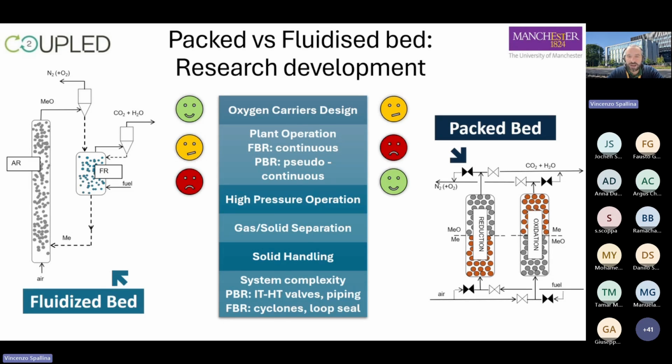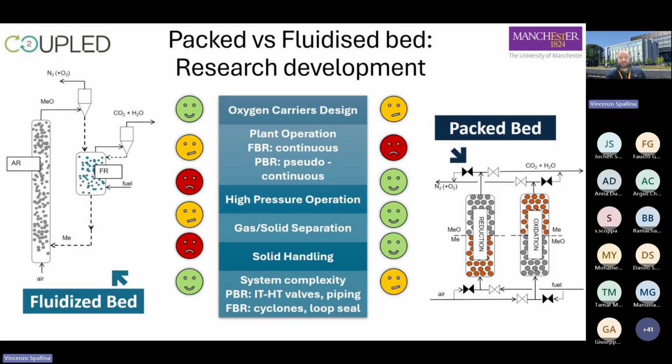On the other hand, high pressure operation is not straightforward with fluidized bed, while it is much easier with packed bed reactor. There is no gas-solid separation to be implemented in a packed bed reactor. There is less solid handling, but on the other hand, there is more complexity, especially when we look at the valves which are needed.